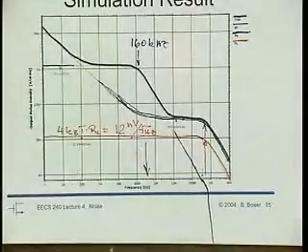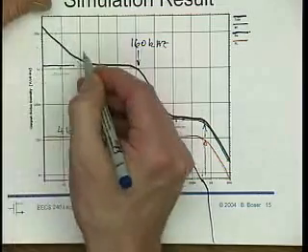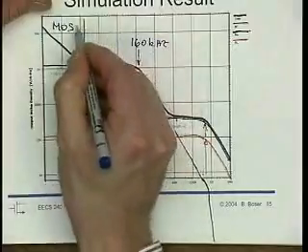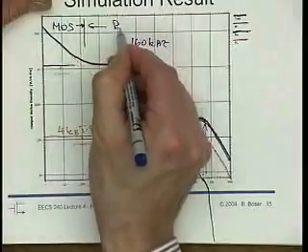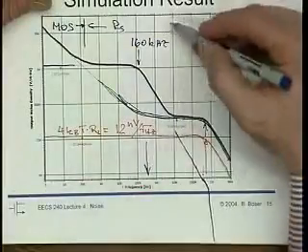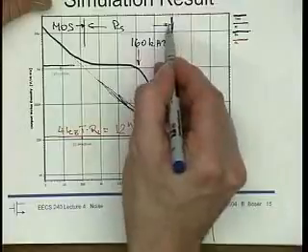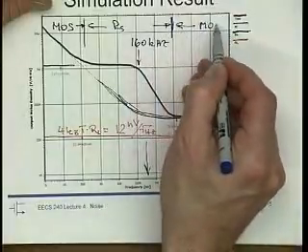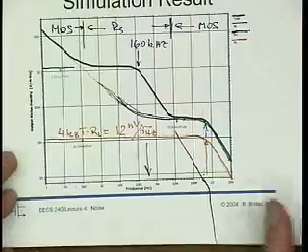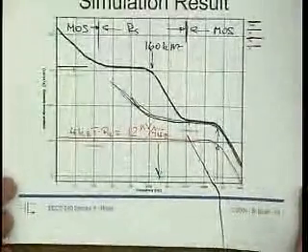So at very low frequency, then it's the transistor. Here it's the MOSFET that dominates. And then here we get the RS that dominates. And then here we get again the MOSFET to dominate our overall noise contribution. Okay. All right. So that's our first noise example.